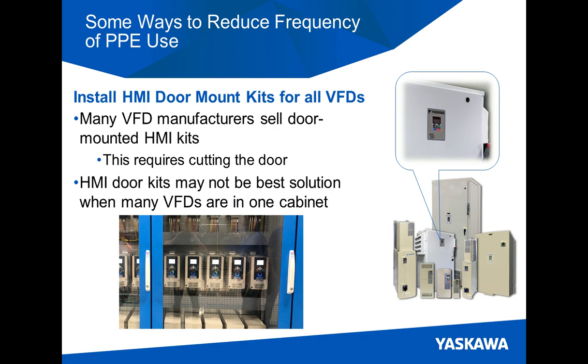So one of the ways to do that, and I don't want to neglect this, is to access the VFD if the HMI or the keypad is mounted on the door of the equipment. And many manufacturers will sell these HMI kits to cut a hole in the door and mount the HMI on the door of the enclosure.